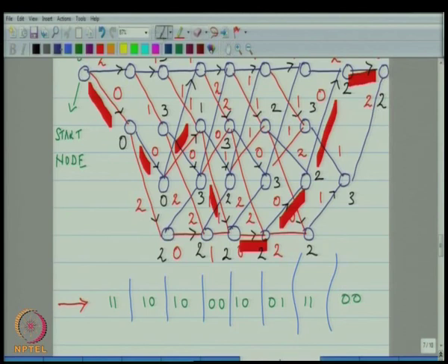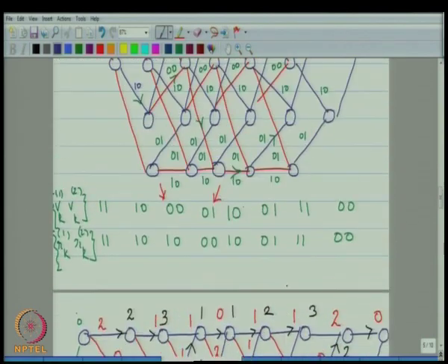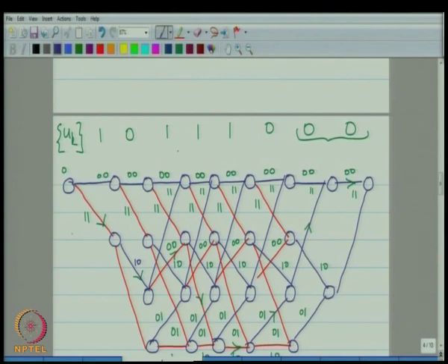So, that underlying message sequence will then be a 1, a 0, a 1, a 1, a 1 and then a 0, 0, 0. So, it is 1 0, 3 1s, 3 zeros. And if you go back and look here, you will find that it is hopefully the same 1 0, 3 1s and 3 zeros. Okay. So, we were able to decode the code,